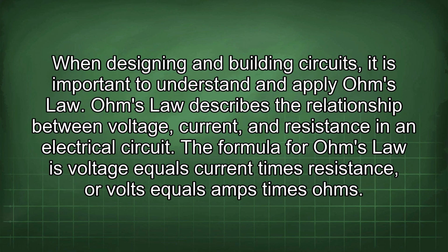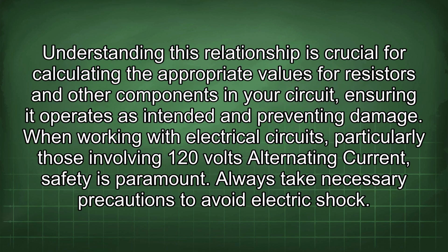When designing and building circuits, it is important to understand and apply Ohm's law. Ohm's law describes the relationship between voltage, current, and resistance in an electrical circuit. The formula for Ohm's law is voltage equals current times resistance, or volts equals amps times ohms. Understanding this relationship is crucial for calculating the appropriate values for resistors and other components in your circuit, ensuring it operates as intended and preventing damage.